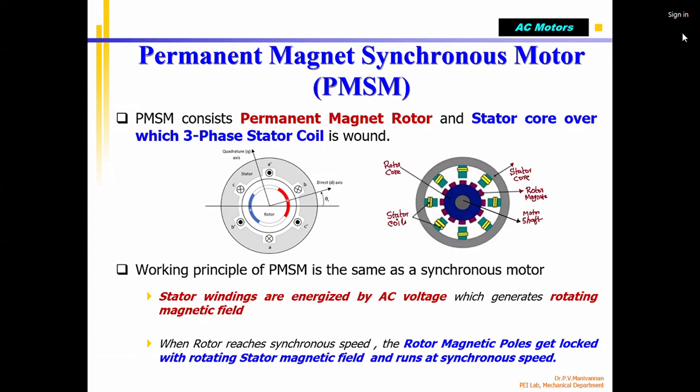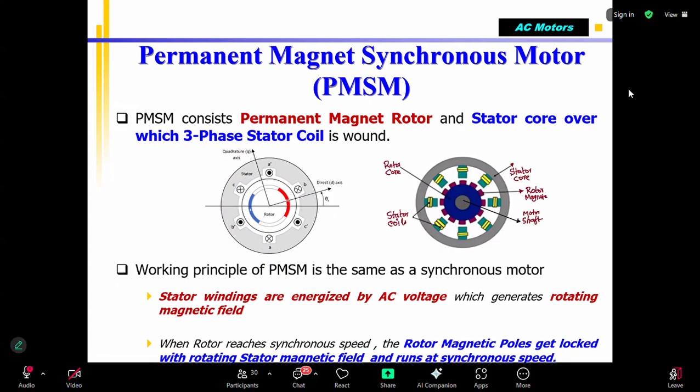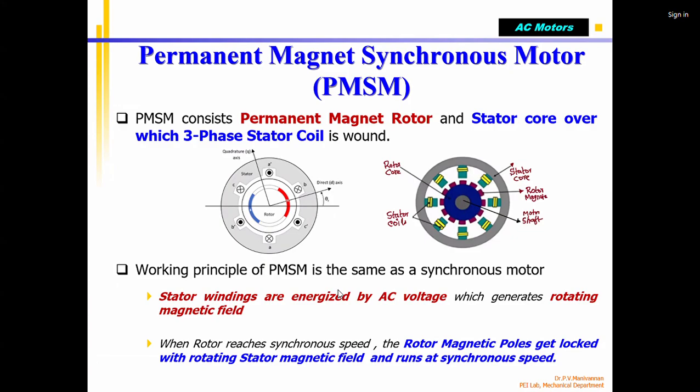These starting coils are fixed on the surface of the rotor and are energized. That generates a magnetic field that makes the rotor get aligned and magnetically locked. After that, the power can be stopped. You don't need an external motor. The starting coil voltage can be stopped, and then the synchronous motor will work.